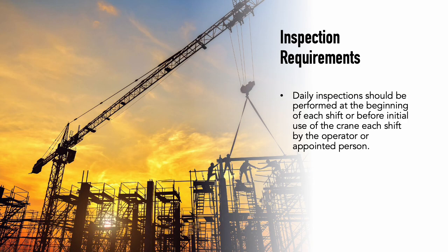Inspection requirements. So it's pretty important that everything gets inspected. Again, the crane operator is responsible for his crane, should be somebody who's knowledgeable and qualified, and then the rigger needs to inspect his equipment daily.